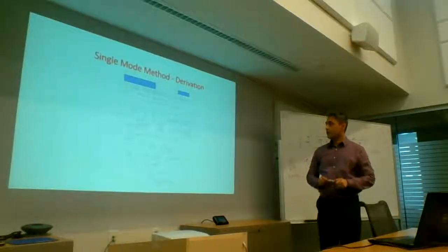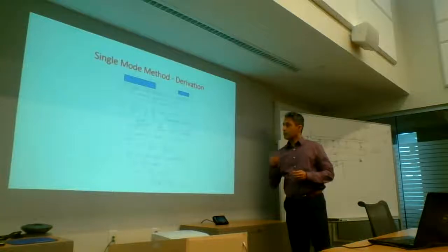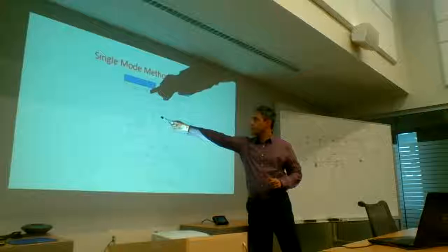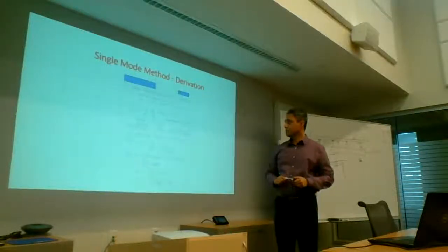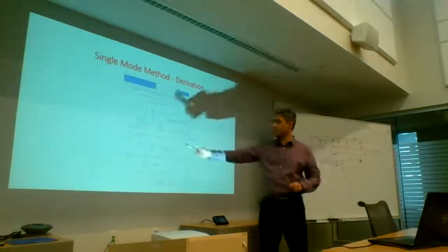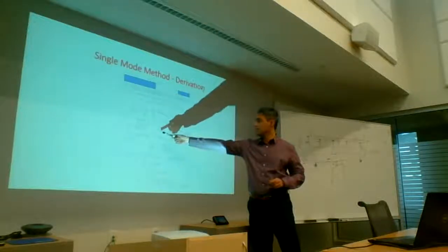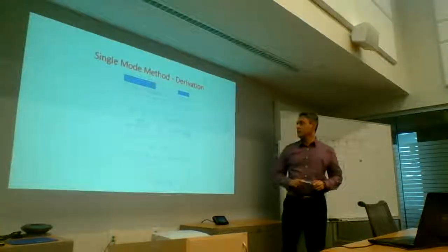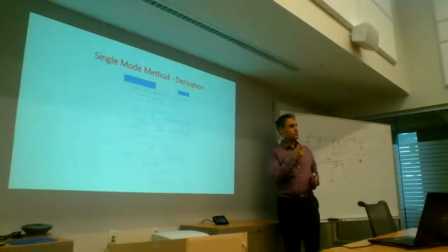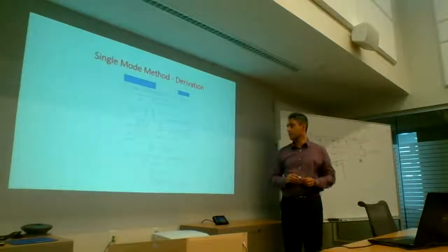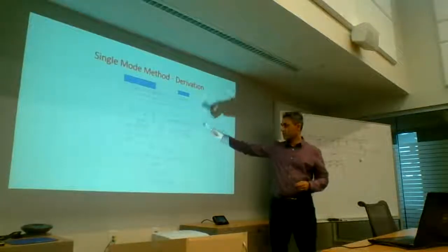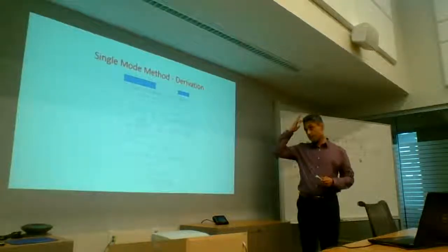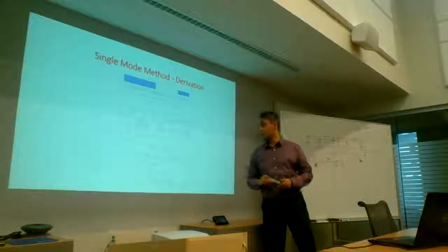And then when you look at modal analysis, your Vx, which is the maximum response, is given by a spectral displacement for unit mass and the mode shape ordinate, and then there's a modal participation factor. And that is dependent on how you normalize your mode shape. So there is a dependency there. So in this case, the mode shape factor is given by an expression which is a product of your mass and the mode shape.